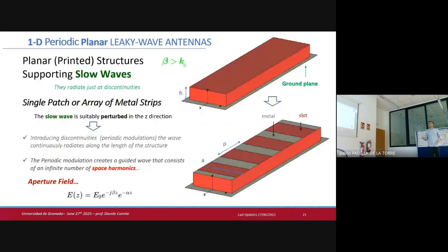This is a generally well-known problem, because before all-metal periodic structures with slots on top, there is a huge literature on this structure, a grounded dielectric slab. Huge literature because you can do this with PCB. So in the 90s, with patch antennas and so on, people started to study this kind of periodic structure, even though the first type of Leaky-Wave antenna was the slotted waveguide.